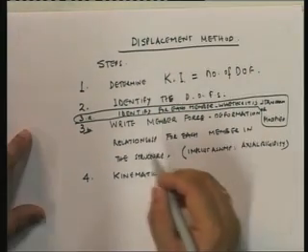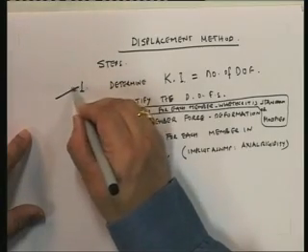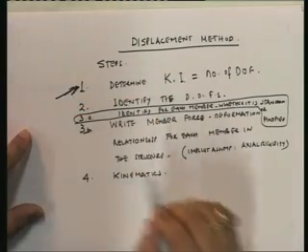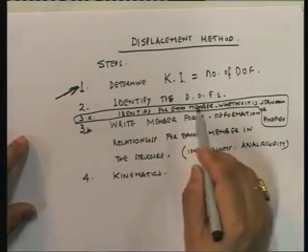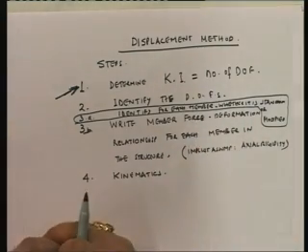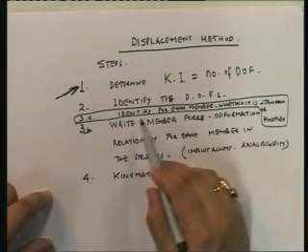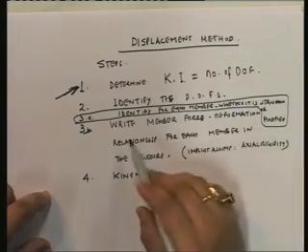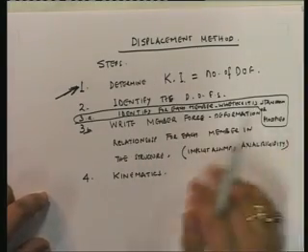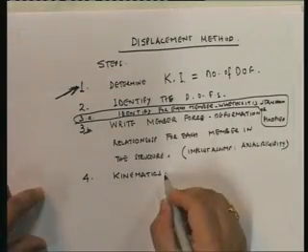See, now the first important step over here is this: determine kinematic number of degrees. After that, identifying the degrees of freedom is not that important. And once you identify the force deformation relationship, standard or modified, is also easy. Writing down the force for each is also easy.